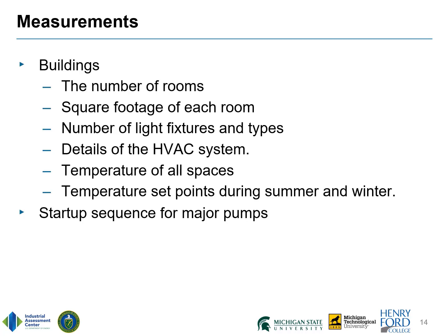Also be sure to obtain the startup sequence for major pumps if that information is not available from the plant's SCADA system. Some facilities may have an electrical monitoring and control system.